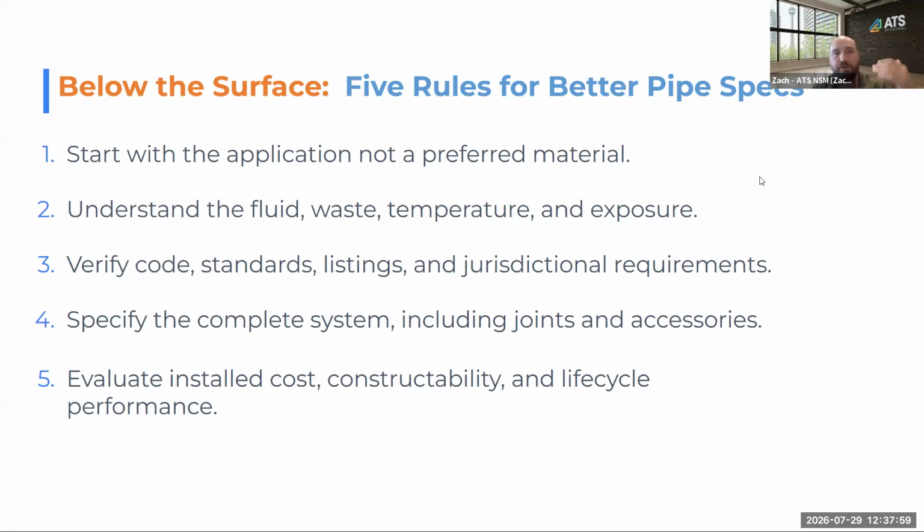So, in essence, to boil it all down, what are the standards that we need to meet? What are the fluids that it's handling? Making sure that we are calling out an accurate basis of design so that there's a proper point of reference for when they are quoting, and then a complete system. Those are really the key points. And then as you're deciding between materials, understanding the complete life cycle cost versus just the dollar per foot.